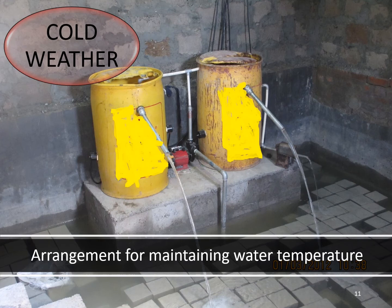You can always circulate hot water continuously inside the curing tank, and you can connect these things with a thermostat, so that the moment you achieve the required temperature, the flow of hot water stops automatically, and then at any point of time your cubes which are there in the curing tank will be in a position to maintain 27 plus minus 2 degrees centigrade for curing purpose.